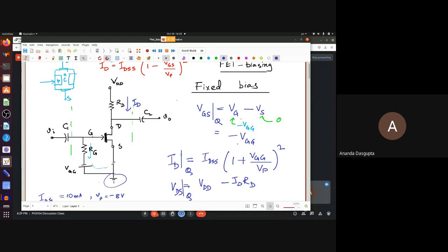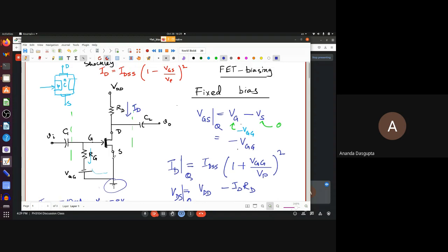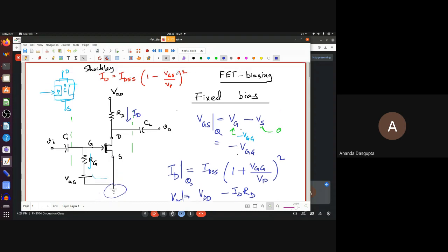Two problems there. What will happen basically is, if VI is connected to the ground, then the gate is really directly connected to the ground. So how much will the signal be? So remember, the gate is where the input voltage goes, and that controls the output, right? That's your Shockley relation. It says that whatever the gate to source voltage is, that controls the ID. Now, if you were to have a short here, how much would the gate voltage be? The AC voltage at the gate. How much of the signal will be across the gate?